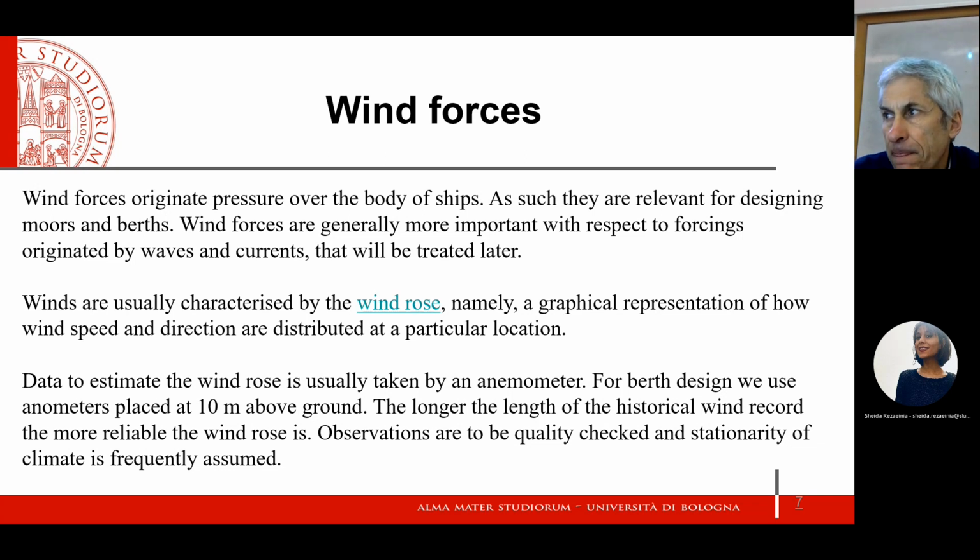Now, so wind forces. What is the big question mark here? It's not really the surface of the ship. The big question mark is to estimate wind. And we rely on observations. Wind is a weather behavior that is extremely difficult to predict and quantify from a technical point of view.